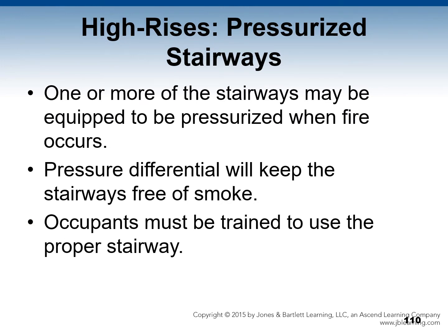Now let's talk about pressurized stairways. In a high-rise, you may have one or more of the stairways that may be equipped to be pressurized when a fire occurs. The pressure differential will keep the stairways free of smoke. This requires a dependable source of power and intakes located so they will not pick up smoke from the fire. Occupants must be trained to use the proper stairway, in the event of a fire.